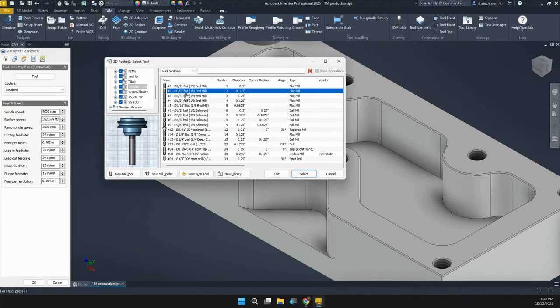So we can use the 3/8 inch end mill. If that was smaller than that, then we'd have to go down to our next size, right? So these go every 1/8 of an inch down until we get to our smaller ones. So I'm going to select that.